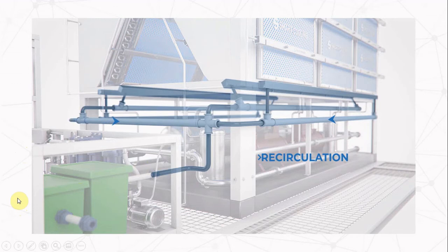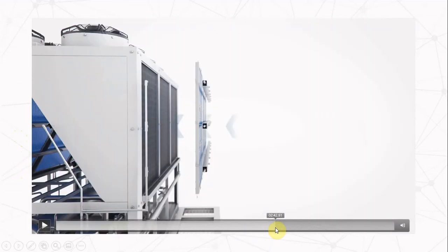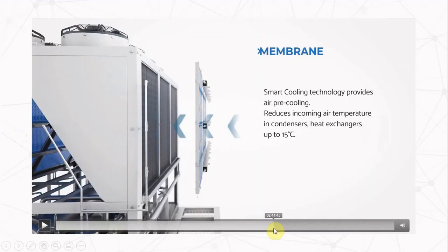We should not neglect the importance of the evaporative protective membrane, which guards the condenser coils from dust and pollution present in the air. This is a key matter, particularly in the Middle East, where air pollution and airborne particles are a serious issue. In this environment, facility maintenance services should clean the condenser coil once a month. You should be aware that it is much easier to clean the evaporative protective membrane of the Smart Cooling device than to clean a condenser coil.